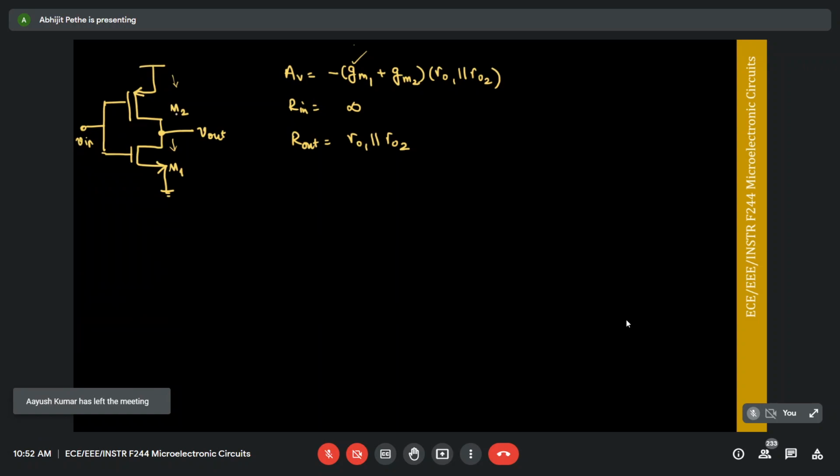So the gain in this circuit is going to be much larger than the gain in a common source configuration, right? So purely from the gain point of view, this is a better circuit, and this is nothing but an inverter. So this is the reason why we use this as a static CMOS inverter in digital design, because this inverter has a high gain, so it quickly switches from VDD to 0. In analog design, we won't use this much. As we go through the class, you'll understand why we don't like a design like this. But for now, just know that this will have a high gain.